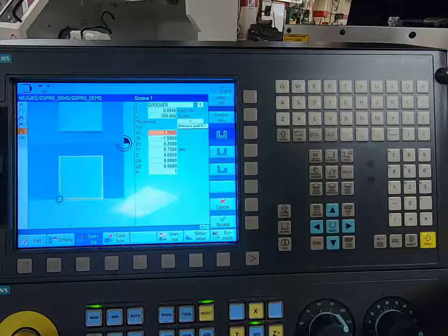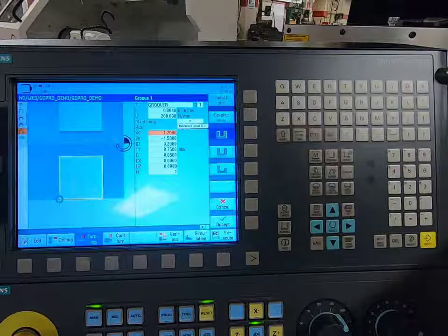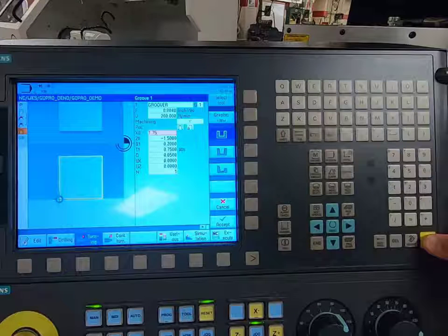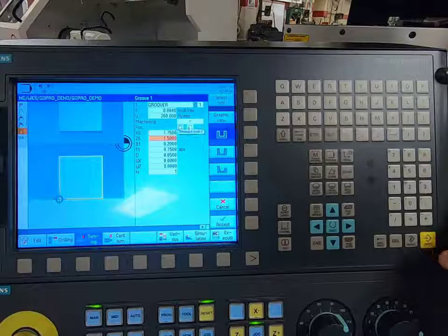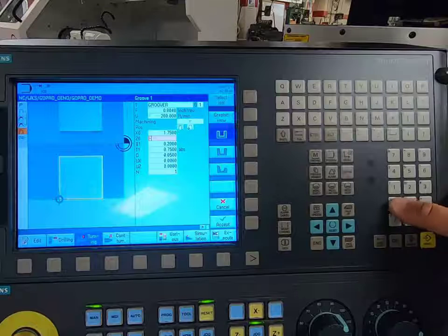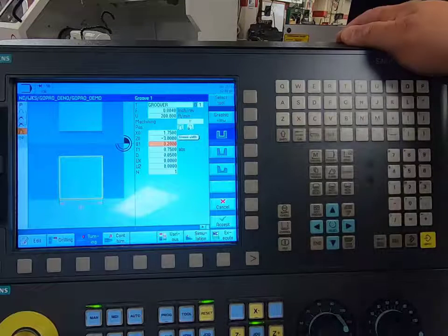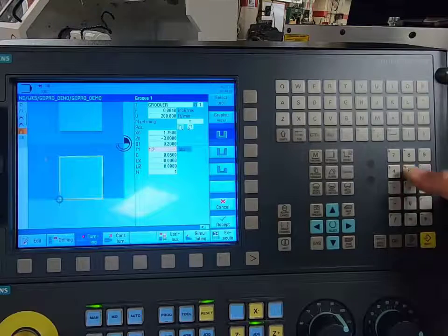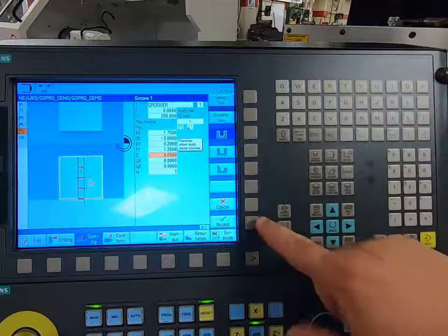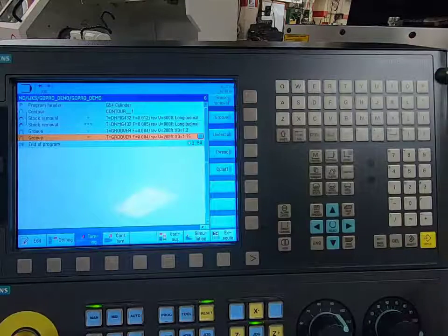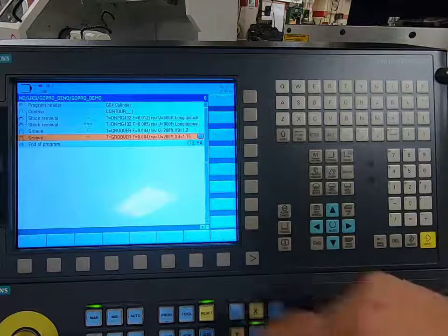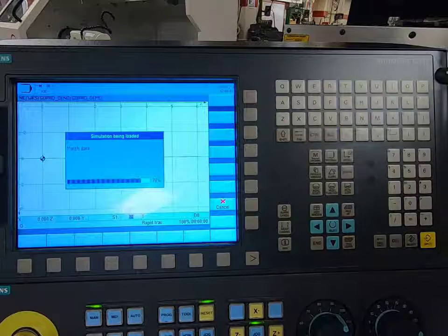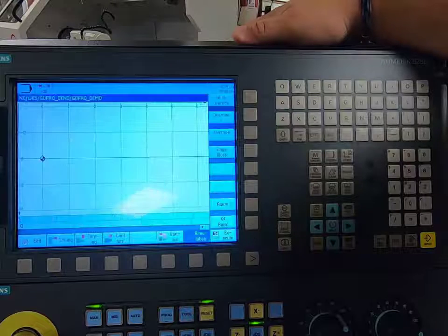Now my X diameter is 1.7 that I'm going up next to, so I'm going to change that to 1.75, giving me 50 thousandths. The location of it is a minus 3 inches. It is still 250 wide, and the finished diameter is 1 inch 250 thousandths. Everything else is the same. I'll hit accept. That was really fast because it remembers everything. So I made a new feature, and now I'm going to simulate it. Now pay attention to these yellow lines for the grooving.